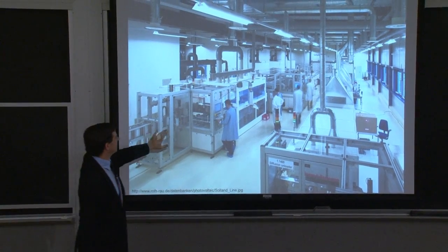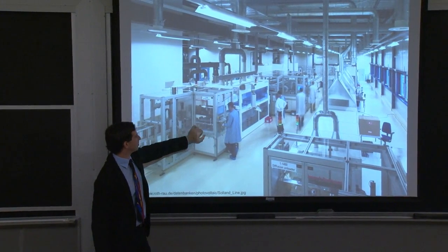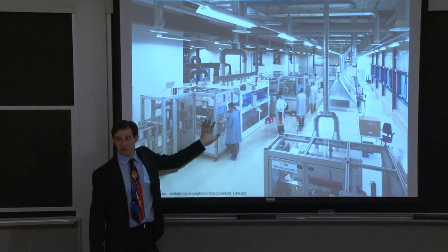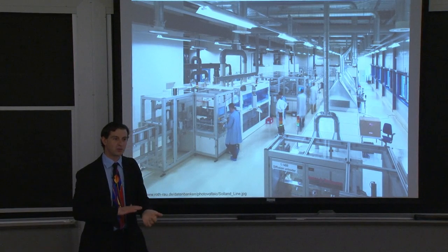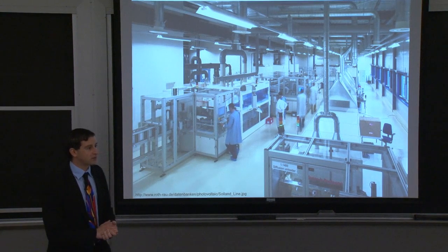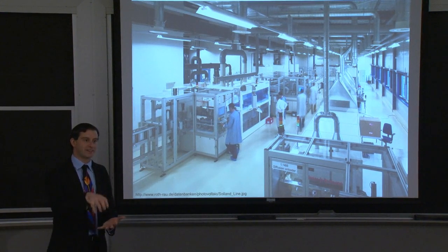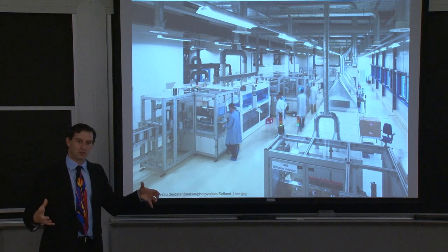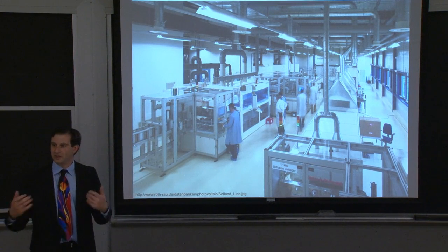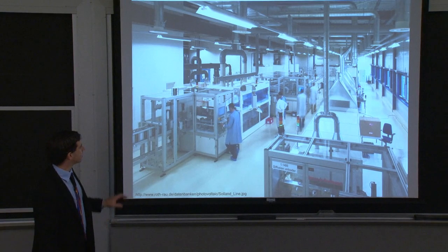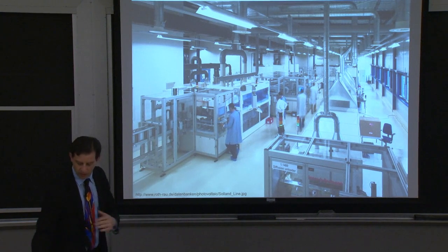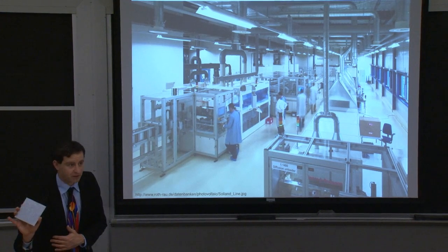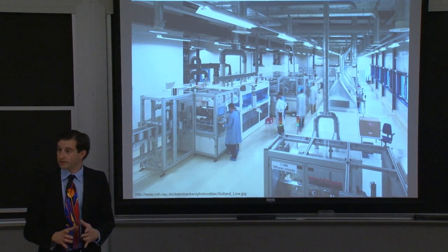Whereas in wafer fab, it was pretty dirty, in cell fab, it looks pretty clean. You have a combination of these inline processes, like this one shown here, where you have wafers on conveyor belts moving through lines, and batch processes, where little robots pick and place, lining wafers up inside of crucibles or boats, and then insert them into furnaces for batch processing. So this is the crystalline silicon cell fabrication. In on one side go bare wafers, like this, and out the other side come fully processed solar cell devices.